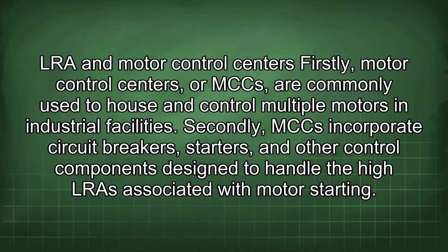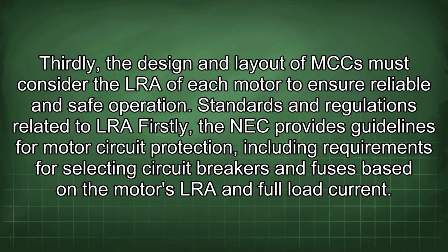LRA and motor control centers. Firstly, motor control centers, or MCCs, are commonly used to house and control multiple motors in industrial facilities. Secondly, an MCC incorporates circuit breakers, starters, and other control components designed to handle the high LRA associated with motor starting. Thirdly, the design and layout of an MCC must consider the LRA of each motor to ensure reliable and safe operation.